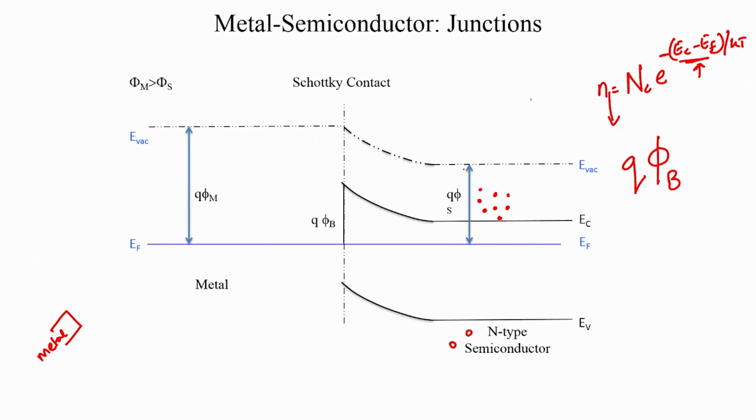Now, in reality, any interface of a semiconductor has a lot of trap states, because that is a place where you have cleaved off the semiconductor, or a place where you have impurities, and therefore you have a lot of energy levels sitting inside the band gap. Because of that, the Fermi levels are not free to move around as easily as described by the mechanics we discussed for band bending, and therefore you have something called Fermi level pinning, and due to that a lot of interesting effects come up, and more likely than not you will end up with a contact that might be rectifying.